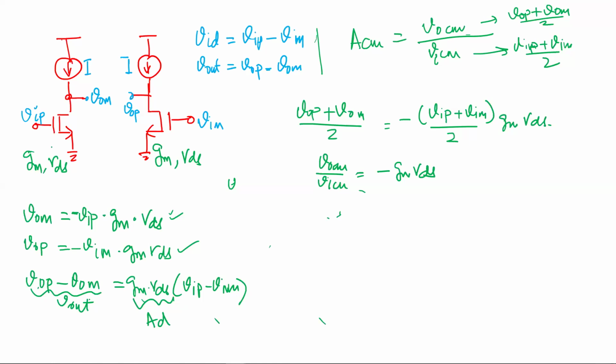Can anyone suggest now maybe we can make a change to this circuit so the differential we want still the same, but the common mode we want to reject, in a sense if there is anything moving in the same direction. Because what's happening is this node, even if I go like this, it's still delta V times GM times R naught, which gets to the output. If I do this, it's still with respect to ground. That's the problem. Okay.